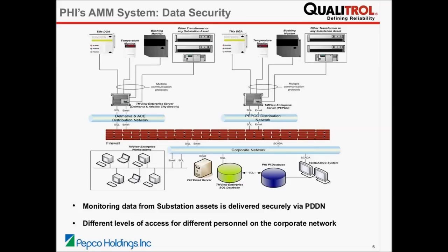And in terms of data security, they did not do rocket science. What they did was ensure that these monitors should not have any direct access from the outside network. So the data from substation assets is delivered via a secured private network, and different personnel have different levels of access to the monitoring data.